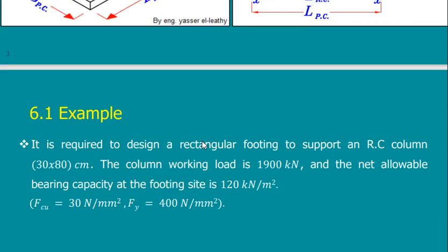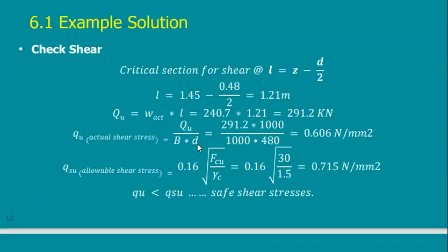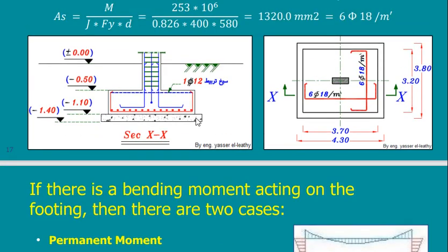I will just show you a drawing to say what I mean here. Let's just check this. Yes, here. This is the part that is protruding outside the reinforced concrete. If I take this cantilever very long, then it will crack, because my footing is pushing on top and the soil is pushing at the bottom, and this is not reinforced. So the soil will push from below and this cantilever will start to crack.